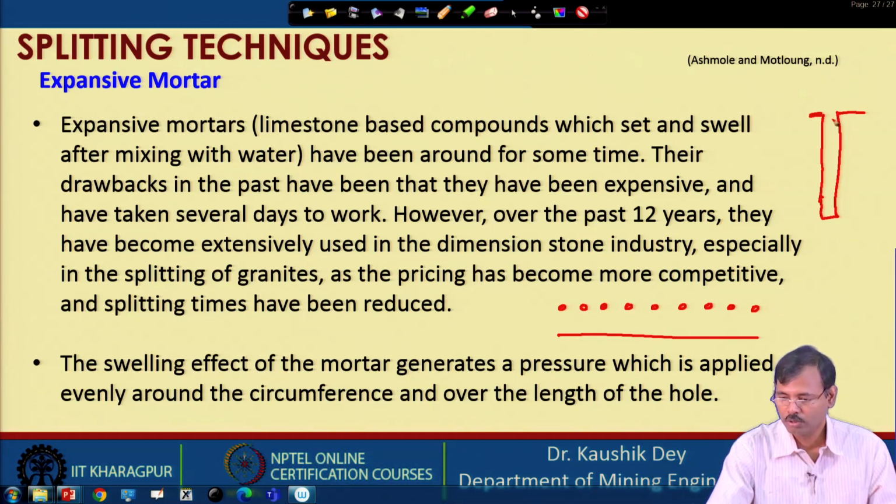So, what we do is fill this using the expansive cement, and after that we may plug it, and then we allow the setting of this cement. On setting, it increases in volume.